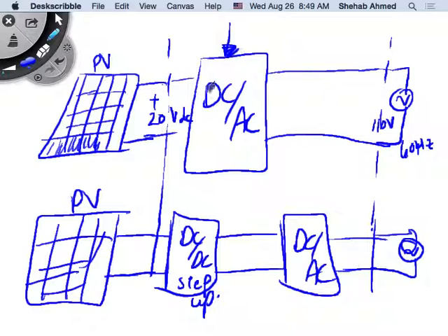This mainly came to life because of what's called microinverters in photovoltaic applications. There is this interest in extracting as much energy as you can from a PV field, photovoltaic field or photovoltaic array. And the best way to do that is to put an inverter in every panel. In summary, that would probably be the best way to do it. The most energy harvesting that you will get is to do that. Granulize it to the smallest granule, right? Extract as much energy from this module, from that module, from this module, and that module.